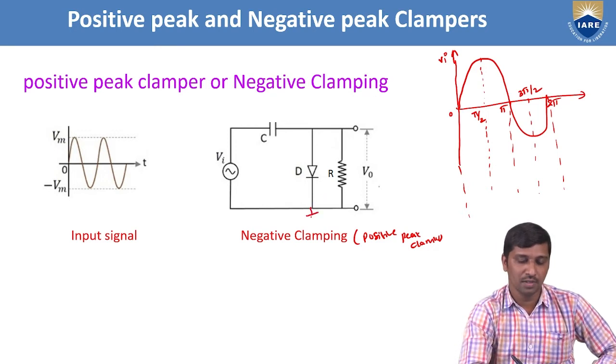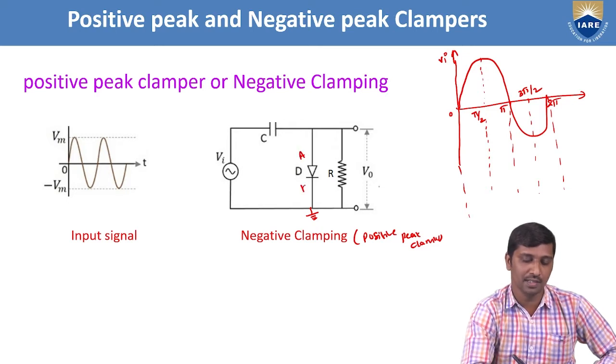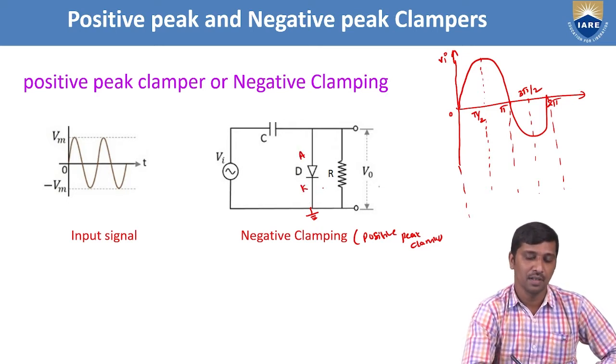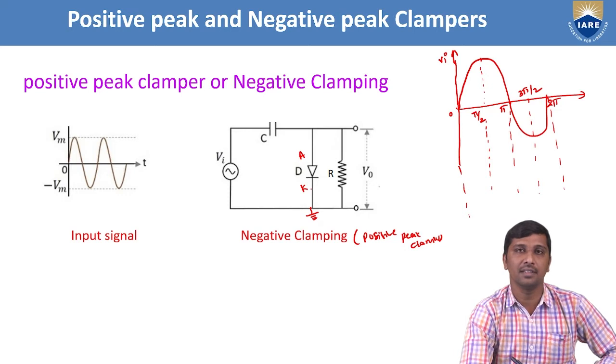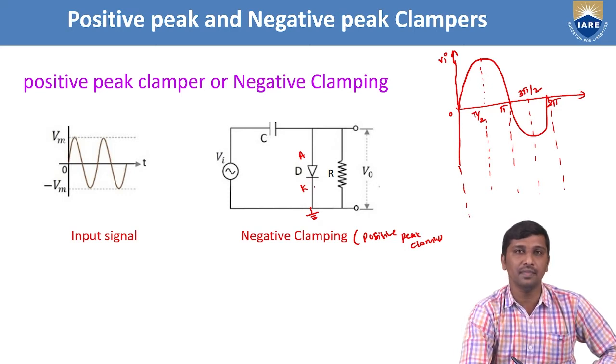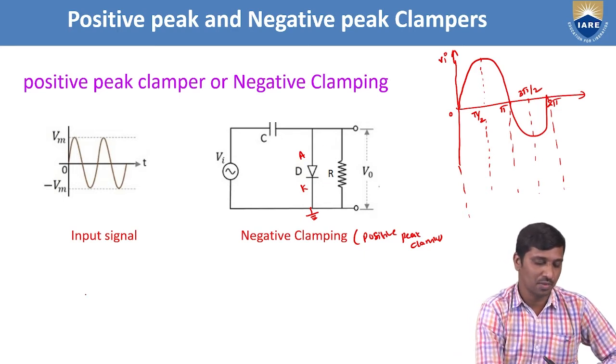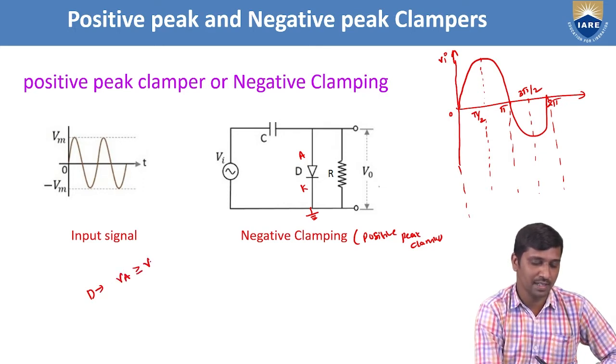Based on the utilization of the diode in the circuit, here it is represented as anode, and here as your cathode. We know that the diode is conducting if the anode voltage of a PN diode is greater than or equal to the cathode voltage. Otherwise, the diode is in a non-conducting state. So for a given diode, we should verify this: the anode voltage must be greater than or equal to the cathode voltage. Only then can we say that the diode acts as a conducting state.